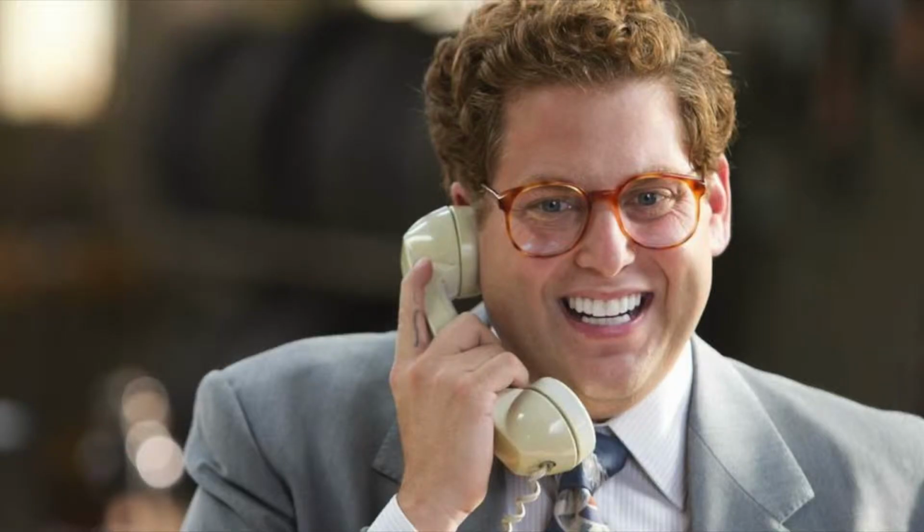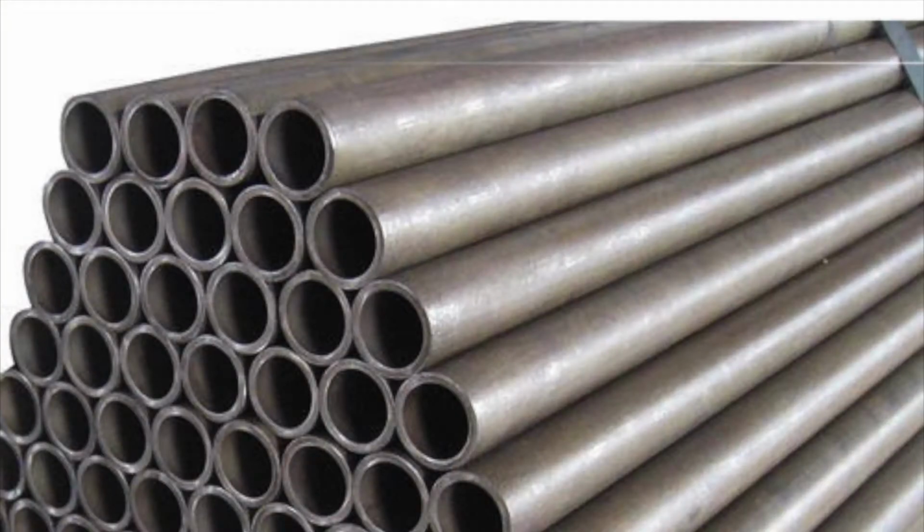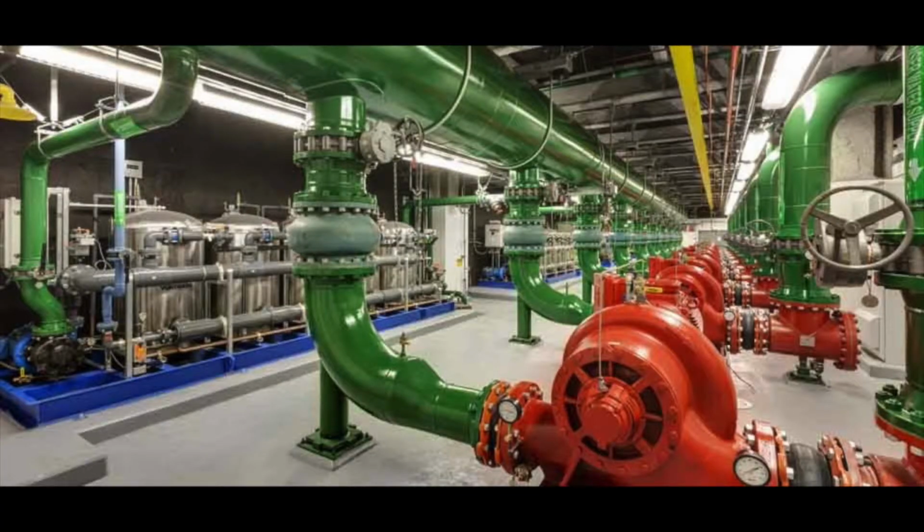Don't worry about retaining all that information. If you get asked about steel pipe for a large job, just ask the contractor to give you the specifications, what the engineer called for. 99.9% of the time in our industry, A53 Type B will cover all applications.